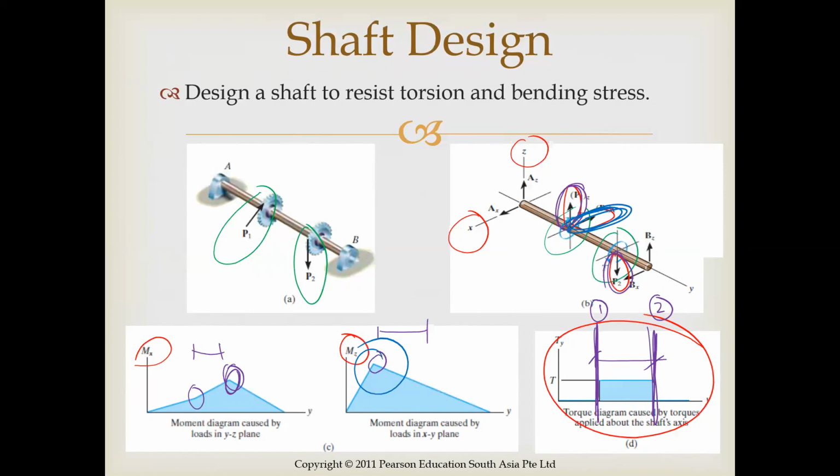And for this one, that's probably fairly easy to get because you can get that resultant moment and then figure out where that occurs. But the problem is if you just take this maximum moment and that maximum moment and get the resultant of that, you're not looking at a particular location. You're taking two maximum values and getting an even bigger maximum, so you're being conservative.